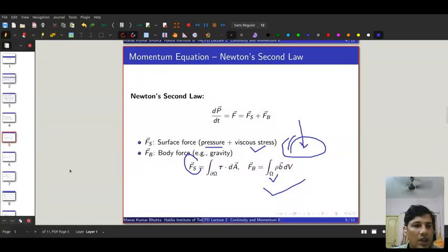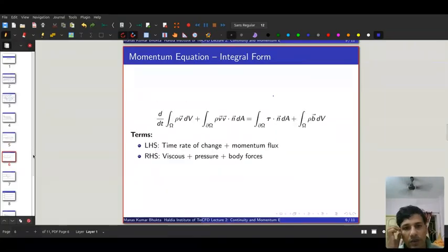So this is the momentum equation of the integral form; now the momentum equation of the differential form. To obtain this local version of the momentum equations, we again apply the divergence theorem, and bring all terms to an appropriate pointwise formulation. We arrive at this equation where the divergence of the momentum flux equals the sum of the body and the surface forces.